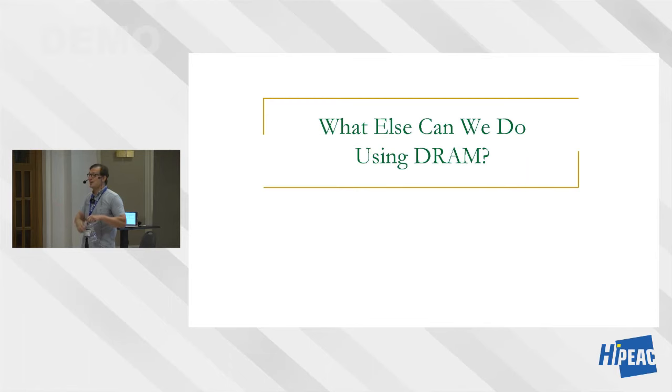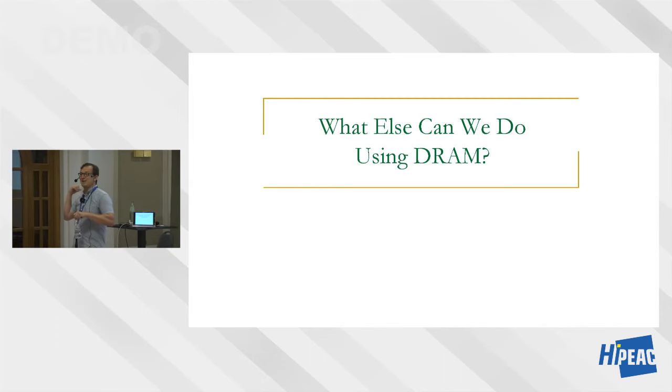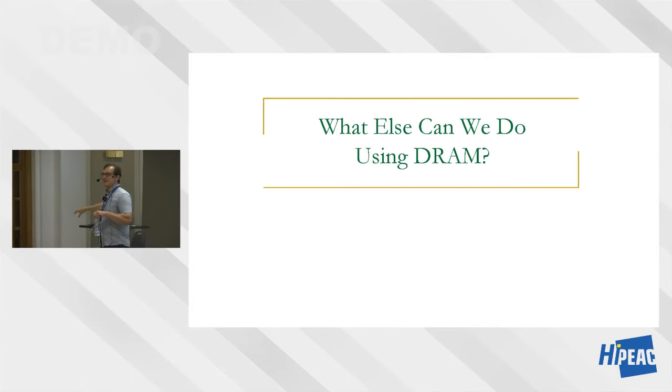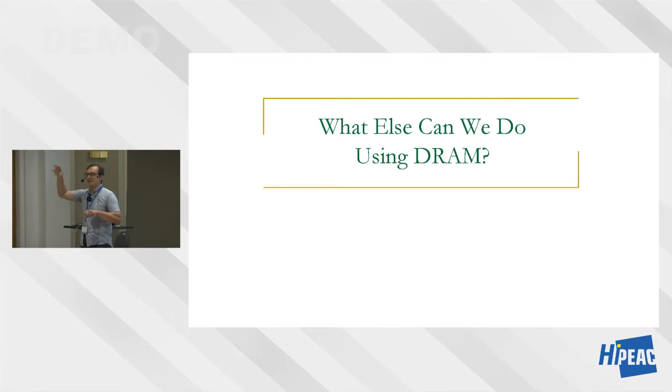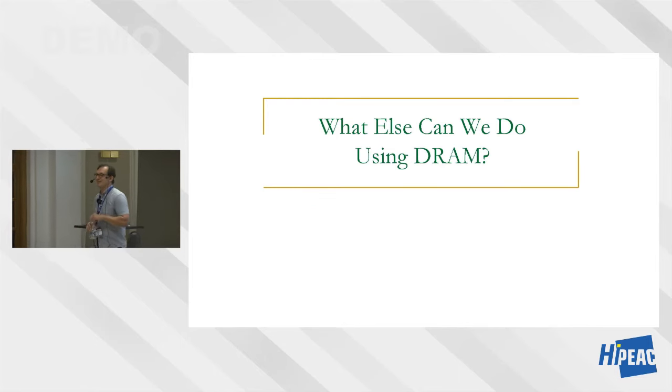If we actually do a complete sweep on the timing, we should be able to come up with a better operating point. But our resources are not enough for that. All of these tests actually take months and months of time. So even our results are conservative in that sense. I believe real success rates are really higher if you find a better operating point. And if you actually know how the sense amplifier and the row decoder are designed, you can actually do much better.